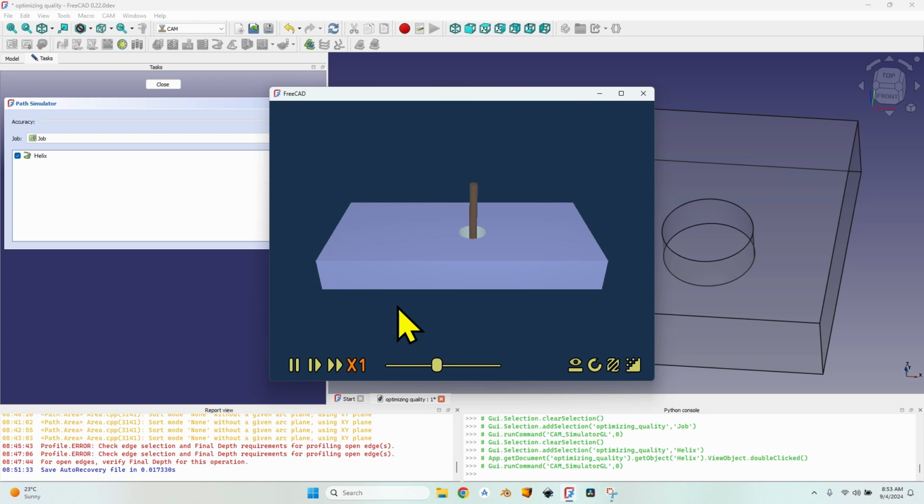If it isn't in perfect condition and doesn't cut absolutely perfect, even when it is in perfect condition, this might happen: it will have a little deflection away from the wall that it is cutting. This means it will be slightly bent to the inside, so the walls won't be cut exactly at the correct dimension because of the deflection.